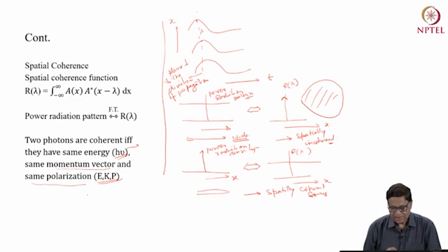So laser devices in general are coherent both in time and space, which means they are spatially as well as temporally coherent. And the benefit of spatial coherence is that the light is in one direction, so you can couple maximum light into the fiber.